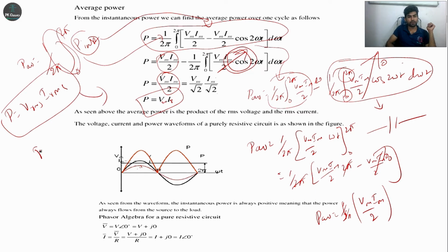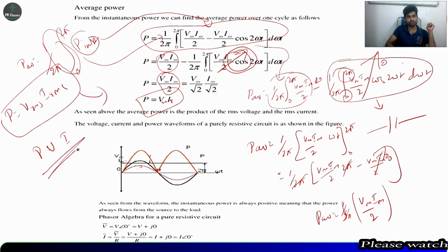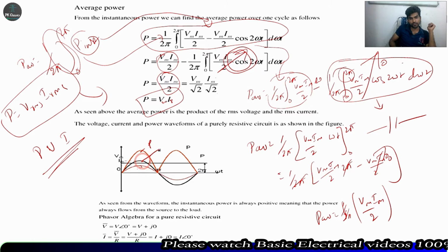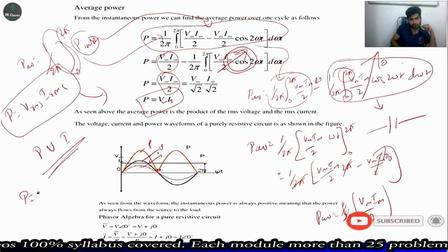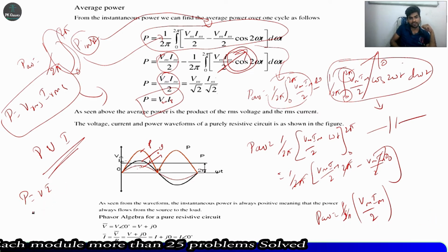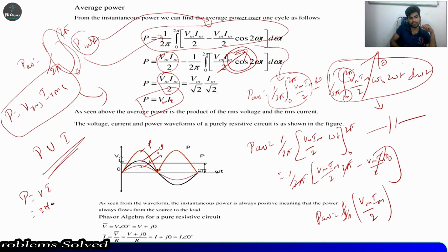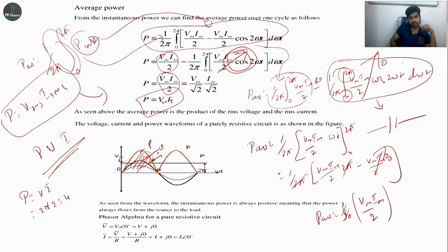Next there is a power, voltage, current waveform. Okay, so this one is power, this one is voltage, this one is current, right? So see, for example, power is equal to Vi. Both are positive, so we'll get power is positive. Suppose voltage is 2 and current is 2, we'll get 4. So power is 4. And again power is equal to minus 2 into minus 2. This is minus 2 and this is minus 2, you get 4 as the answer. So you get the same power, right? So always in a pure resistance the power is positive, we will not get negative power in the pure resistance.